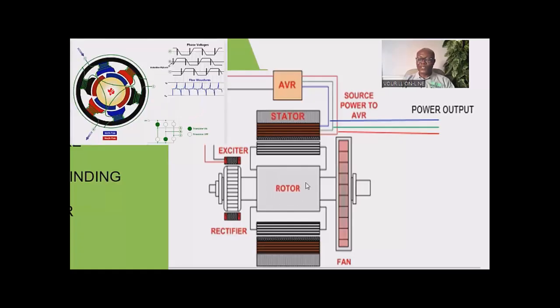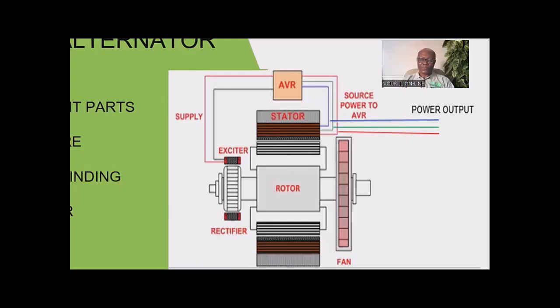So that field winding that is magnetized, since it's rotating, will induce voltage, or EMF, into the main generator armature, where we eventually get our output from. If you look at this, this exciter is called the rotating exciter unit. Okay, there are some generators, and remember this generator too is a rotating field generator. There are some where we have the field to be stationary, like we said earlier.